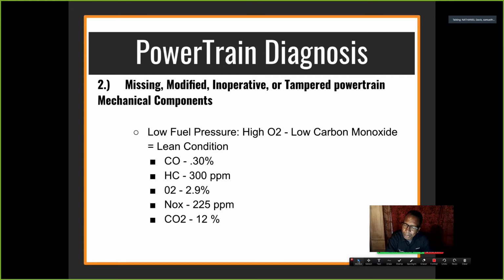So okay, well, hold up. What fumes are you talking about? Well, the ones that are going through the exhaust pipe, right? You're talking about the exhaust fumes after combustion, right? After. Okay, we're talking about the O2 sensor? Yes. Okay, now with the O2 sensor, we have an exhaust leak in front of the O2 sensor.